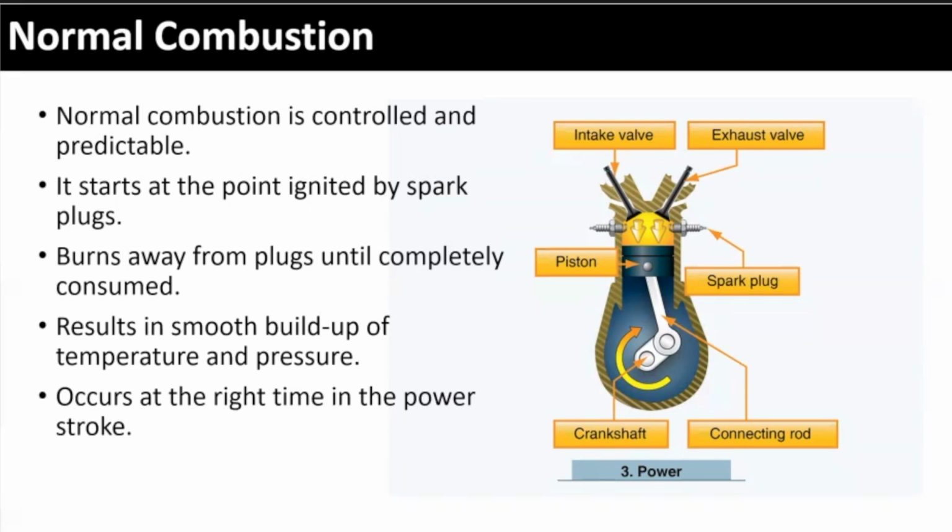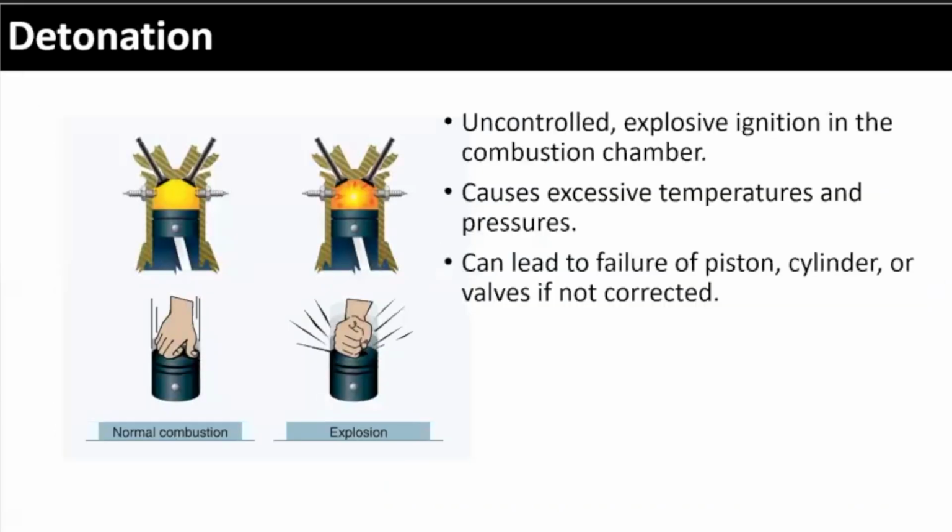We have this thing called detonation. What happens with detonation is it's not smooth, right? It's a very uncontrolled explosion. Not normal, not what should be happening. That can lead to piston failure. It can lead to various problems with your engine. And a lot of that can be caused by using the wrong grade of fuel.